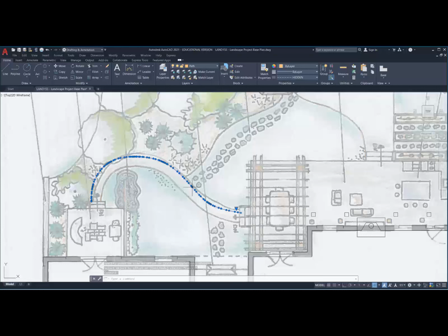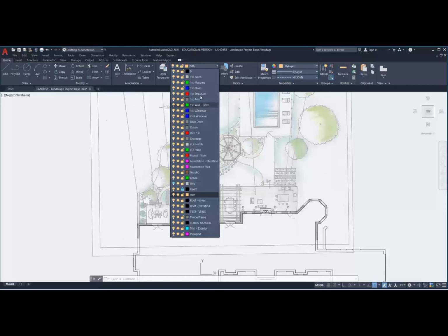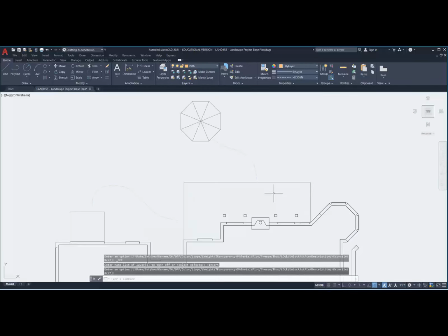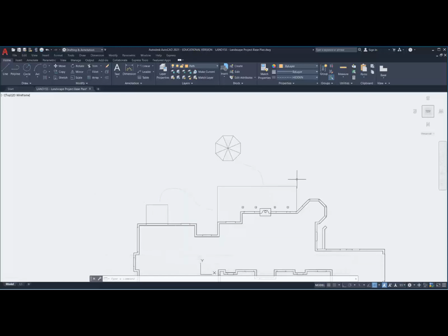The problem with offsetting splines is you get these multiple points. So sometimes it's easier, rather than offset, to draw another spline against the curve, and then you work from there. So let's see what we've got so far. In the layers menu, I'm going to go to the insert layer and turn it off. And there's my CAD drawing with all the details in precise locations that are measurable, where we're now using CAD in its intended method as a precision tool.